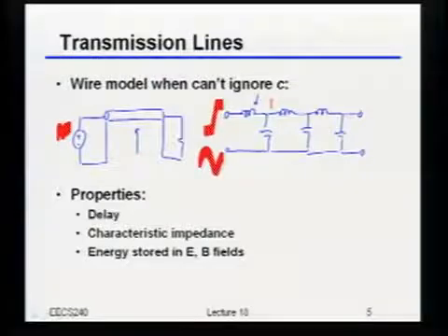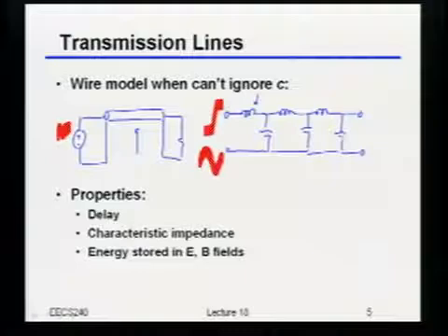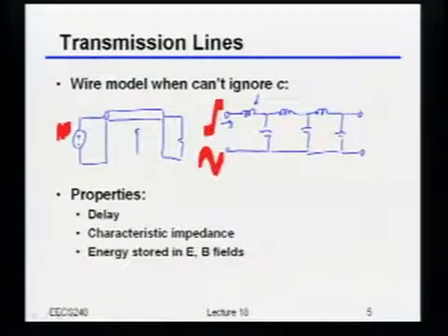Well, the good news is, and this is one of those classic EE240 kinds of things, since I haven't put any resistors inside of this model, which obviously isn't exactly correct, but we'll come back and fix that in a second, there's no way for energy to actually get lost. It all has to be stored inside of this wire somehow and eventually show up at the output.